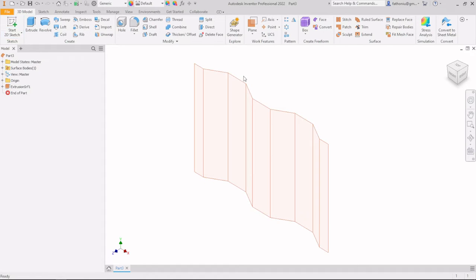We select this one. Before that we escape to cancel the command, and then we set the plane first, the working plane. Select this one, and this requires two lines, so that one, and then you can see there is 90 degree from the selected face here. So we select the line, and then after that we select the face. So then there is 90 degree here, and then okay. So then we construct this working plane here. Then after that we do the sketch, and select this working plane here, highlighted Work Plane 1, select.